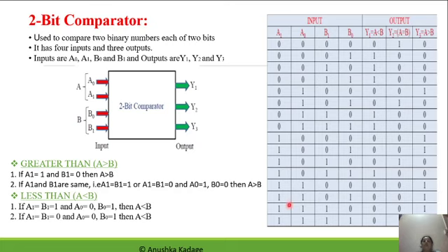The same situation is going to be checked out in the next input combination, where the LSBs are compared. LSB of A is greater, but MSBs of two numbers are same. So based on LSB greater value, we can comment that A is greater than B. So corresponding output will be set.